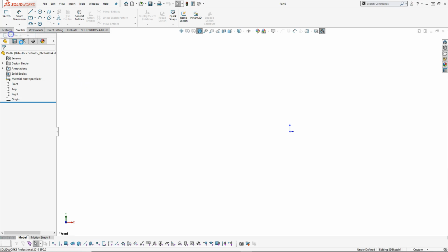All right, so 3D sketches are one of those. Be careful with them. Expect that you will build a 3D sketch up to a point where it starts over defining, and not necessarily any rhyme or reason why it won't do what you want it to do. And when I get to that level of complexity, you save that sketch. You say, I'm happy, I've built this as far as I can go, open up another 3D sketch and add on to it. So there may be a natural point where internal geometry and external geometry go into separate sketches. This one shouldn't be that complicated, so we'll see how it plays out.